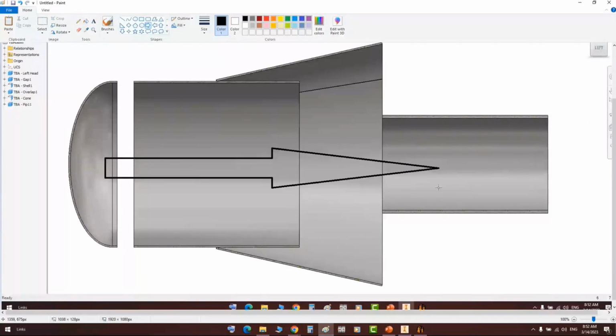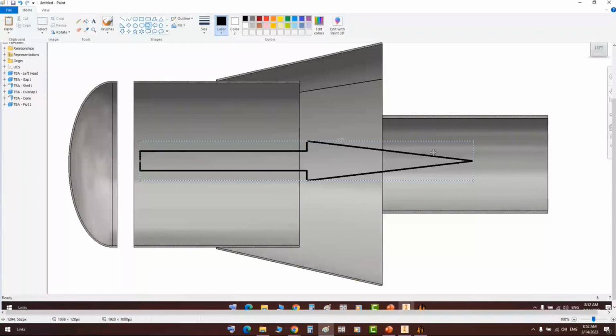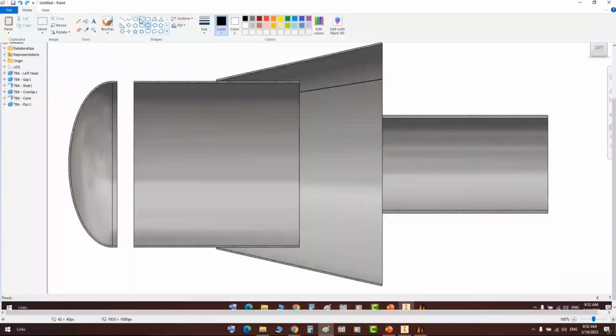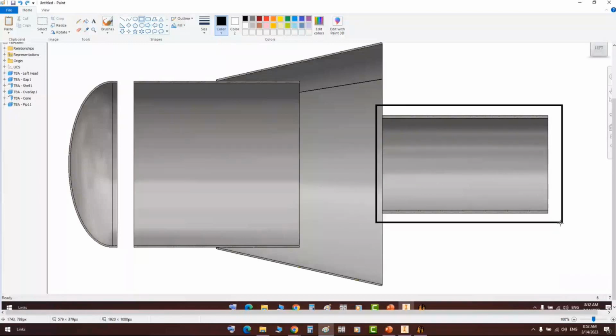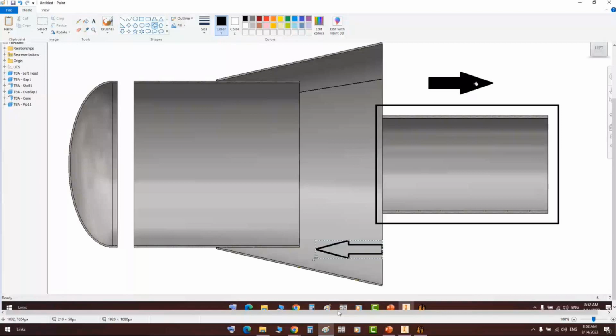Now if you would like to make this element only, which is this shell, go in that direction, you need to flip the direction of this element and make it go in the other direction. Start from here, but go in that direction. To make that, you will need to use the flip order. At this point, you will flip the direction of the assembly.